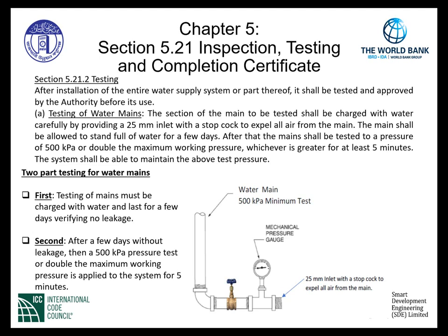After the mains have been set for a few days, then they need to be tested to a pressure of 500 kilopascals or double the maximum working pressure, whichever is greater, for at least 5 minutes. The system shall be able to maintain the above test pressure. So if you read this, you are looking for a two-part test here. The first part is testing of the mains.